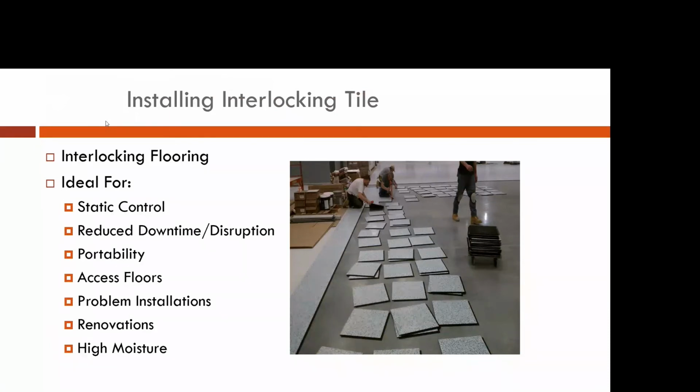The other beauty of interlocking floors is, if you have an existing space, well, that's a terrible space to go into and shot blast a floor and create FOD, which you need to shot blast in order to properly prepare for epoxies or glue down materials. You don't need to put a moisture barrier down, so you're not going to have to test for moisture. You don't have to worry about that.